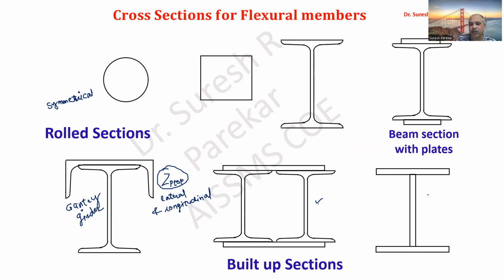Plate girders we are going to use for low or medium loads, but with a larger span. There we are going to use these flexural members. So we should know these beams we use for less bending moment, that is load is less and span is less. If there is a little increase in this, then we will go with beam with plates, then gantry girder. And when bending moment is larger, we will prefer welded plate girder. And after that, we will go with double beam sections.